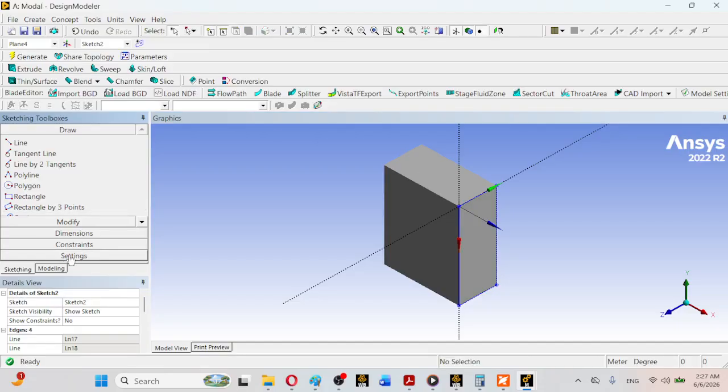And how the sketch will be created? So I had used it here. You can create a fresh rectangle coincident with the edges of this existing volume, or you can use in the modify menu this duplicate option.